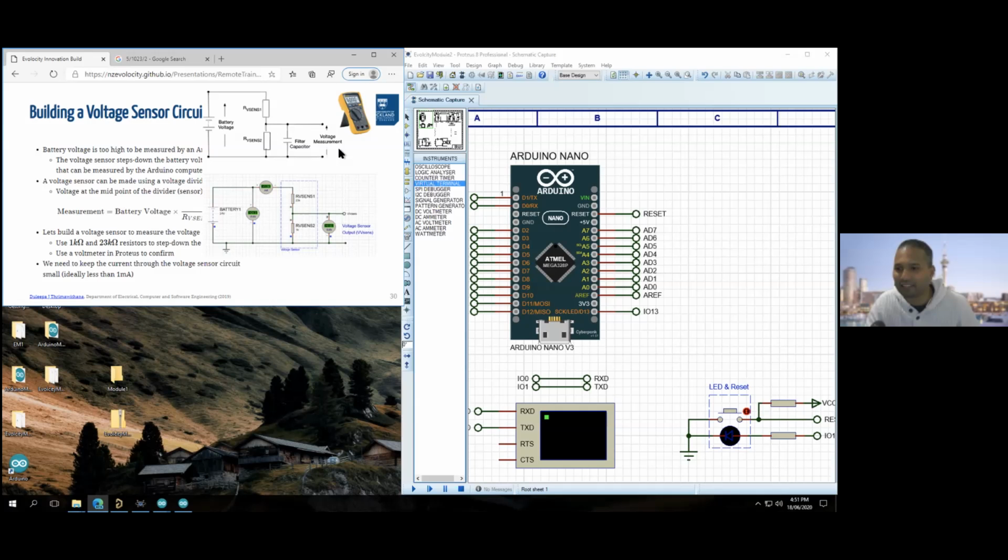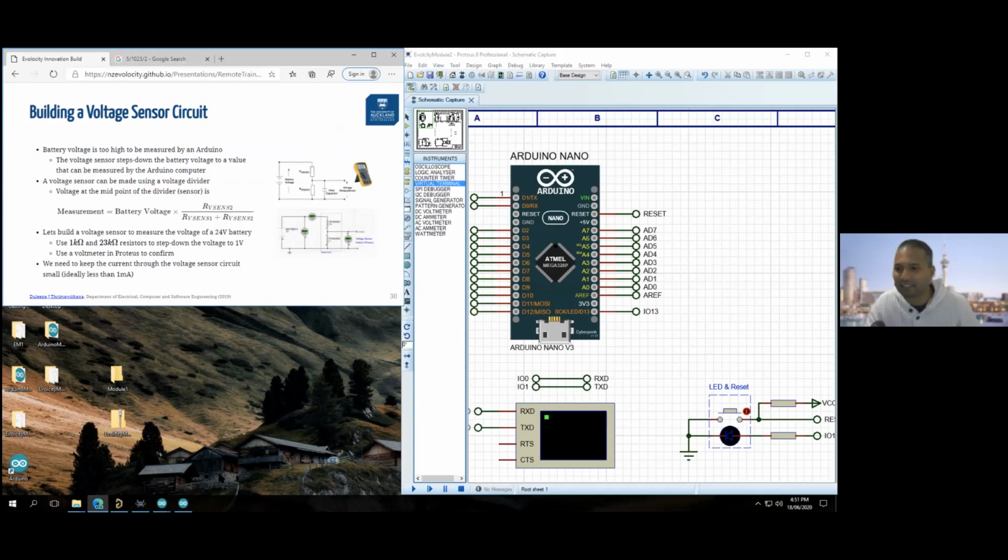I don't quite understand how they know, so to speak, to take half of it. So if you put 100 volts in, would one of them then take 50 volts and the other the other 50? If they're exactly the same size, yes. Think about this. If you have 5 volts, and then you have a resistor and a resistor, each one is 1 kilo ohm in terms of resistance, right?